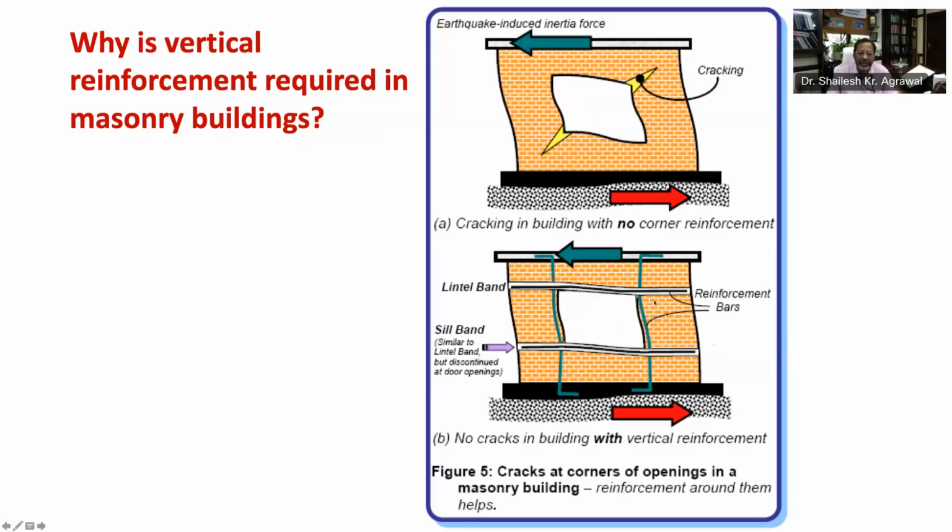And also it is a good practice to confine masonry with bands and vertical reinforcement in and around openings. This is all about earthquake tip number 15.